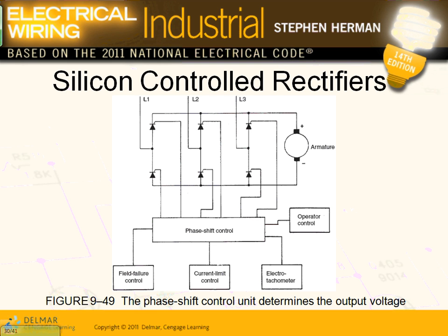The whole idea is to get you speed control on a 100 horsepower motor. So here's a DC motor, wired from a 480 AC system through a DC drive. I have a DC drive that converts the AC to DC, and I have controllers to tweak the voltage, and I'm running it across 100 horsepower. So long story short, guys, that's if you have a DC motor right now.